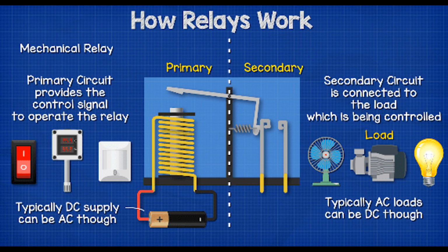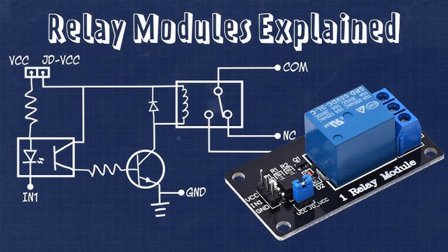Disadvantages: limited to DC applications. Due to its reliance on current polarity, polarized relays are typically restricted to DC circuits. Complex design. The addition of a permanent magnet and the sensitivity to polarity make these relays more complex than standard electromagnetic relays. Application-specific use. Since it operates based on polarity, its application is often limited to specialized fields.